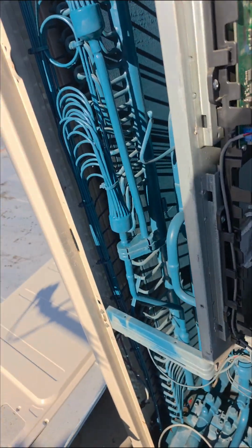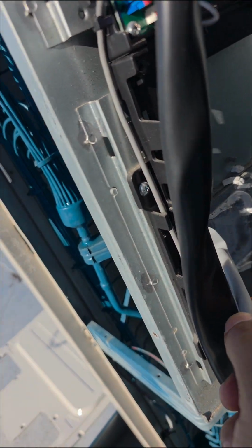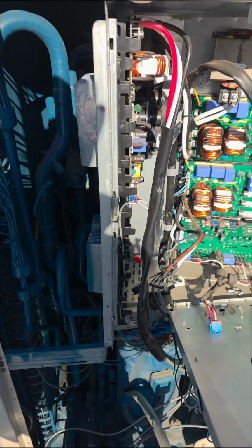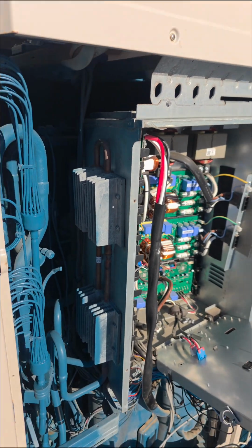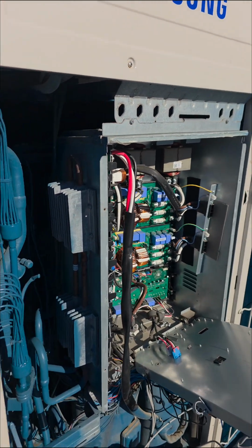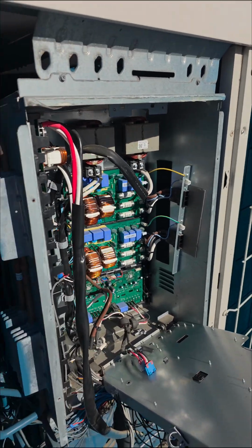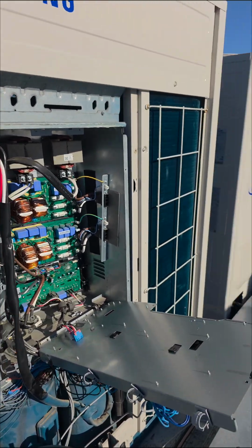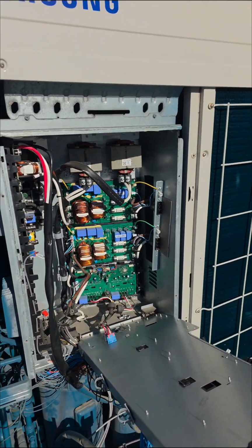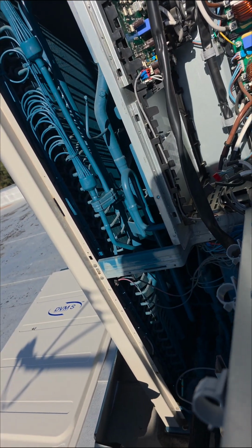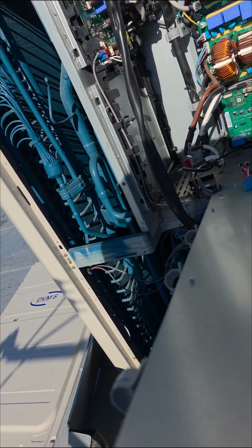You've got a heat exchange over there, an expansion valve, and that primarily is to increase or improve subcooling. So this line is not cold coming to the PC board, but it's definitely cooler than the IPM. So temperature, as you guys know, cold attracts heat. It will move from a high temperature to a low, so we're still able to absorb that heat from the circuit boards.